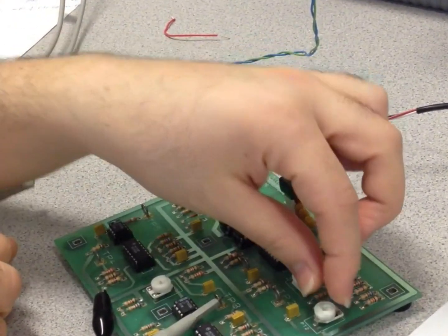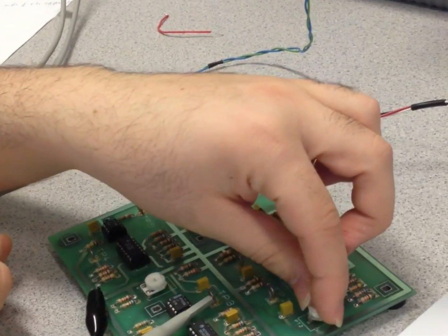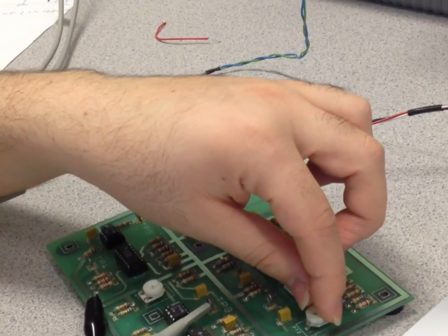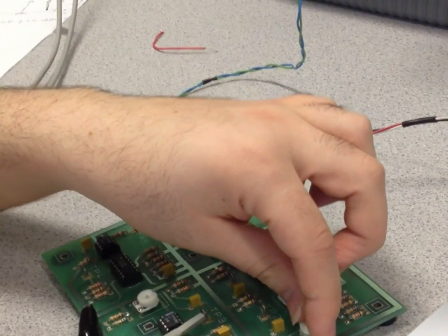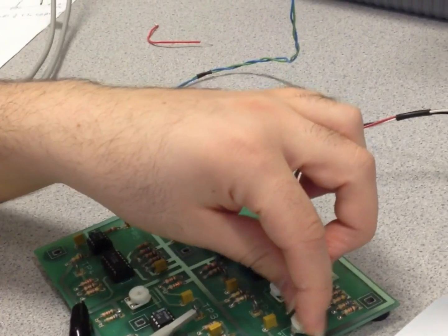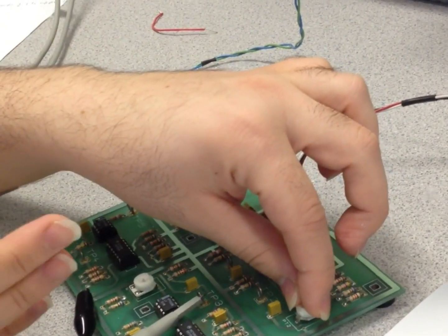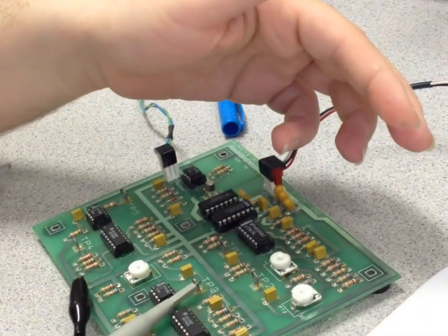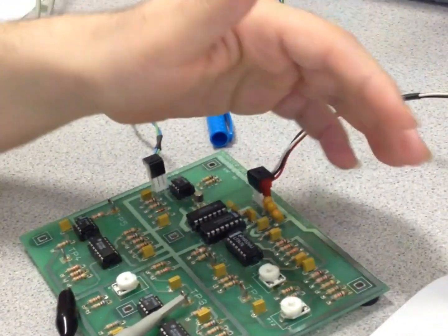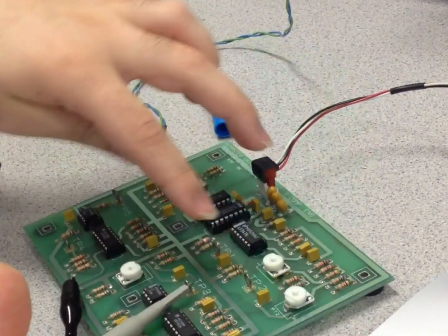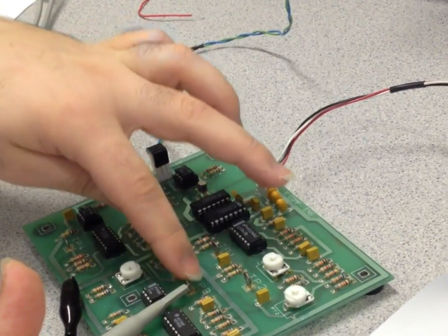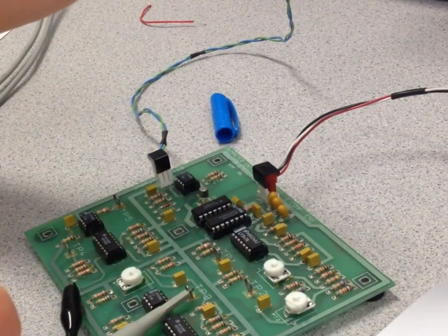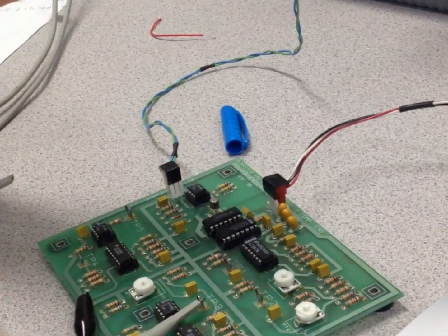For my carrier, I could control the amplitude of the carrier here. The amplitude of carrier, I mean the constant beside the message, which is multiplied by the carrier, is as if it is the DC offset of the message. Using this DC offset, as I said before, makes the signal all positive, which allows us to use very cheap demodulation circuits. Here we have the modulated signal. We saw it in time domain, we saw it in frequency domain. As we see in frequency domain, we have two peaks for the message and the peak for the carrier.